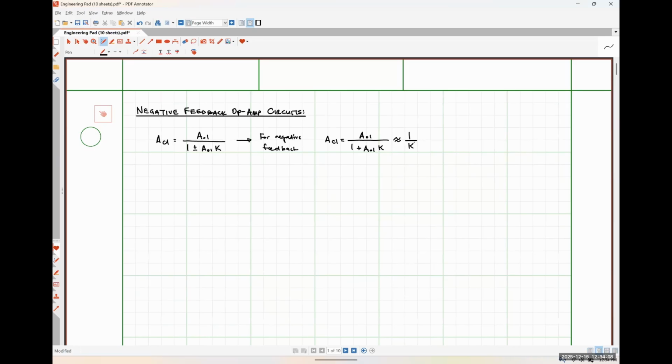So the reason why this is so important is because, and I believe I mentioned this earlier in the class, we might look at a data sheet and see that a typical value for the open loop gain for the op amp that we bought is 100,000. But that is a statistical average, right? The one that we actually bought might be 200,000, or if it was really part of a bad production run, it might only be 10,000 or something like that, right? So just because we know what the typical value of the open loop gain is, doesn't mean we know what the actual value is, and it can have a pretty good amount of variation, okay?